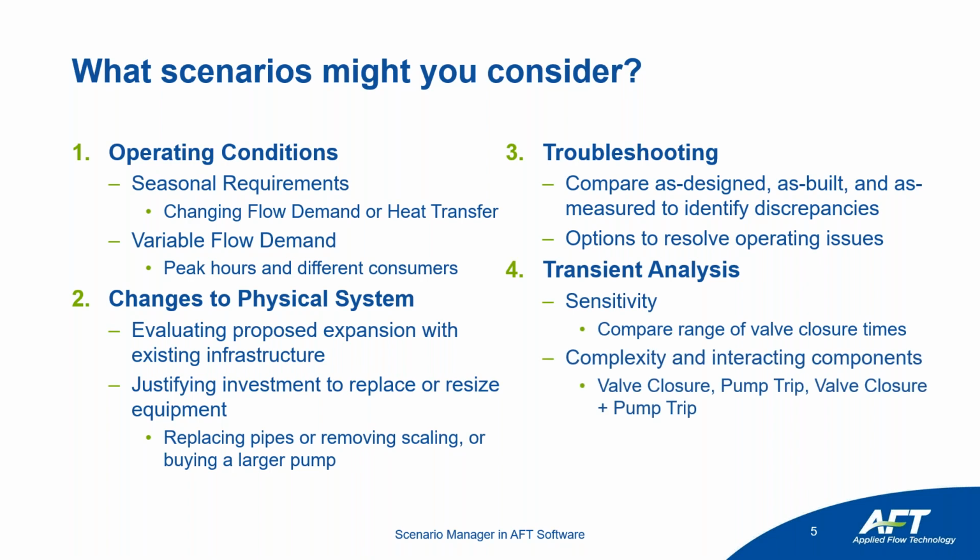And then the final case is that transient analysis, where we can also do things like sensitivity. So in transient analysis, think of transient analysis as surge pressures and forces. So if you slam a valve closed, all of that kinetic energy of the fluid suddenly turns into pressure. The more gradual you can slow that fluid down, the less pressure response you should anticipate. And so the easiest variable that you can change is how quickly you're closing that valve. So you might do sensitivity, you might create a range of scenarios at different valve closure times, evaluate them against each other, and figure out that way what scenario is best or what is going to mitigate those surge issues to an acceptable level.